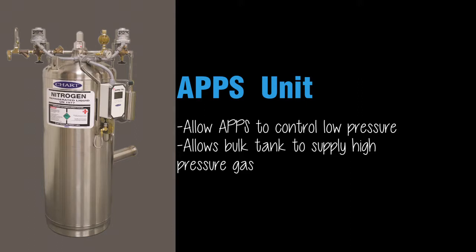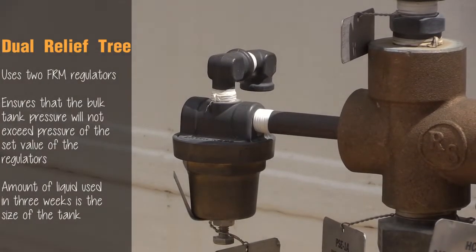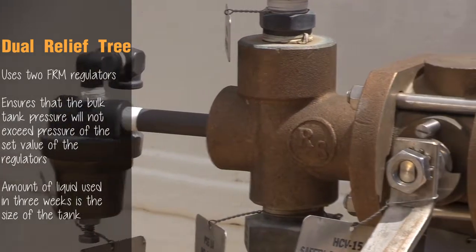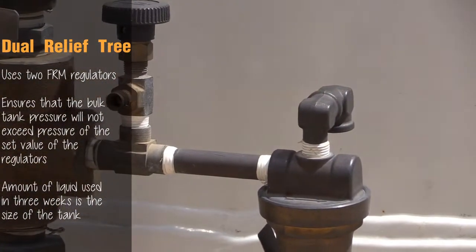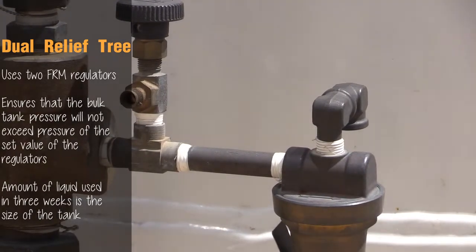If the system is supplying liquid only and the pressure of the liquid is critical, the tank should be equipped with a vent to atmosphere regulator system. This system employs the use of two FRM style regulators, both set at the top side of the desired operating pressure. With one on each side of the dual relief tree, this ensures that the bulk tank pressure and liquid will not exceed the set value of the regulators.